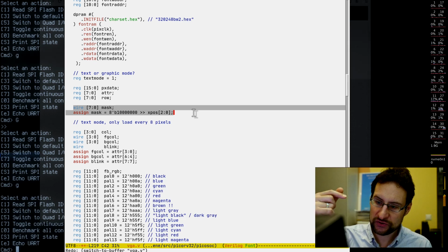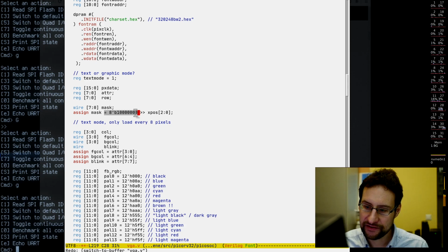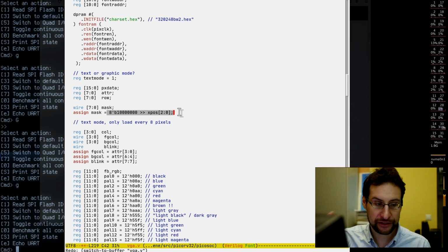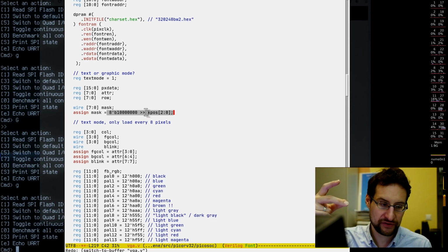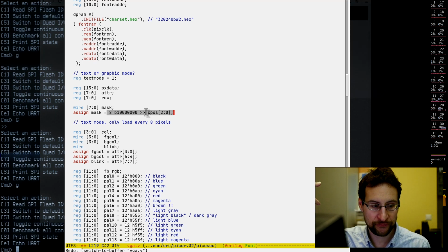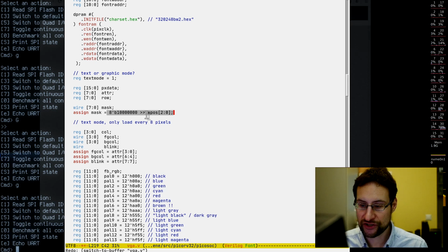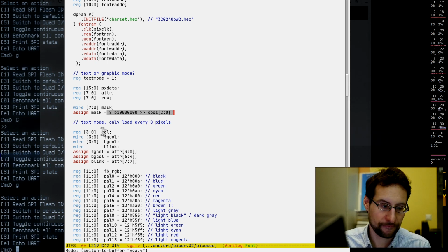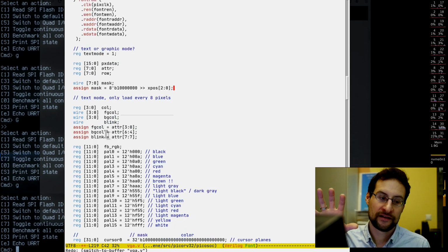This mask is used, as you see, for masking the text character, and it is much more efficient to hardwire this. This is a hardwired shift right directly from the output of this X position register, running always with the full clock and instantly flipping those bits as soon as the bits change in the register. This is updating, of course, with the propagation delay of the logic elements, but instead of having this one clock cycle later. And this is also the magic here.